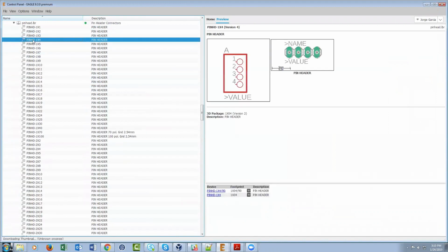Now, somebody stated that you have something on the download library. What you could do is that you need to have the download folder as part of your path in Eagle. That's one way to go about it. Or have that library in use. Well, first of all, it has to be in your path and in use, both of them. That takes care of that.